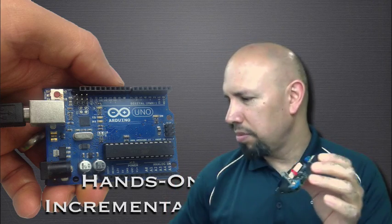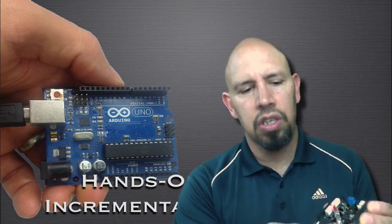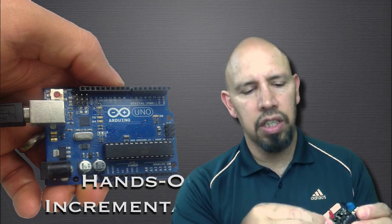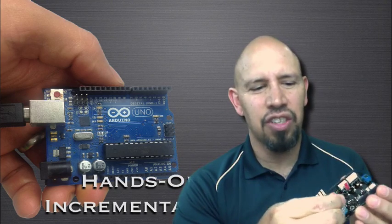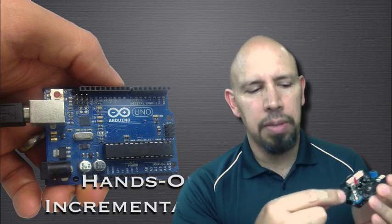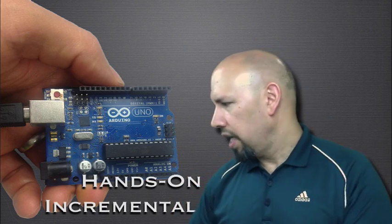One of the problems of these little guys when people try to use them directly is that you need a fairly secure physical mount to this thing, or else it will have problems. If you just try to use this on a breadboard and stick those little pins in the breadboard socket, you're going to end up having trouble because the thing won't stay in there when you're physically trying to turn it. So it's nice having it mounted on some kind of physical breadboard, or an actual physical circuit board to work with.